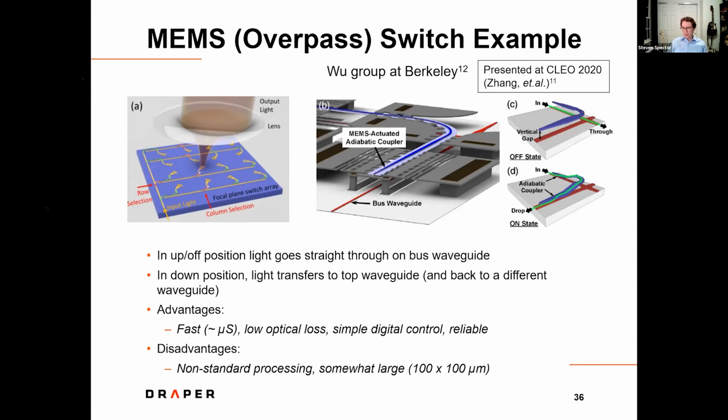They first developed these switches, I think, for telecom or datacom applications, to make an add-drop network. But they realized that they could use this for LiDAR too. So you basically have a row-column matrix, just as we showed. The light comes in here, you have row selection, the first set of switches, and then along each row of waveguide, you have column selection, another set of switches. The switch doesn't emit the light though. It connects to a grating, which then emits light towards the lens.